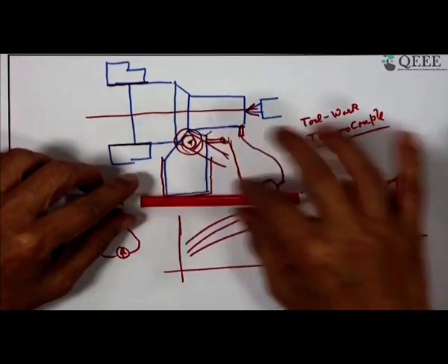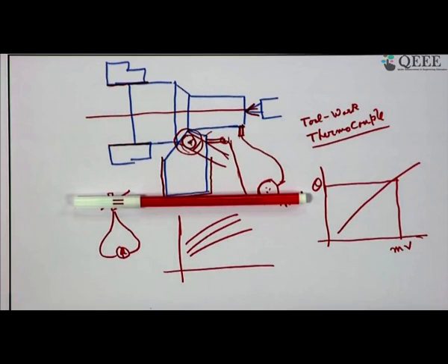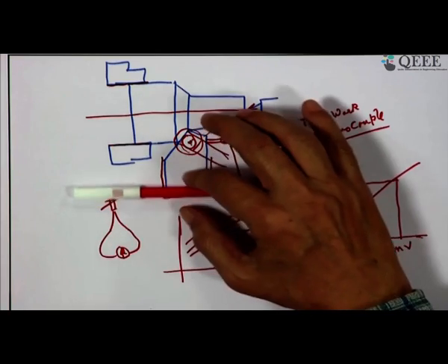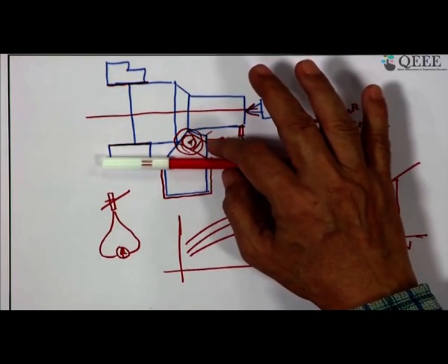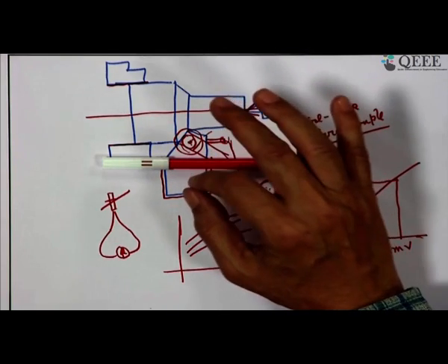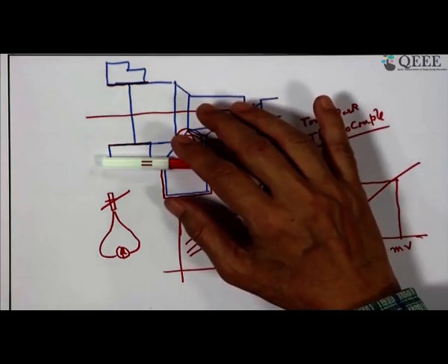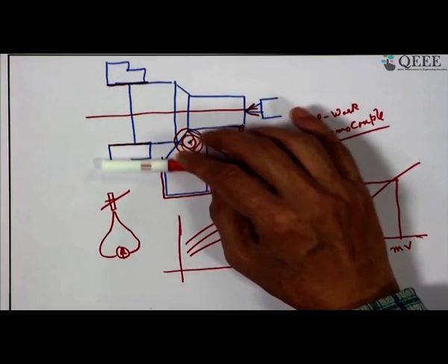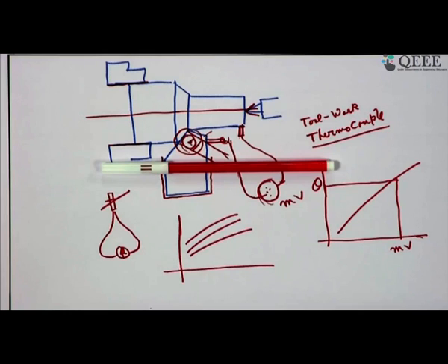Number 2 is that if you do not attain high cutting speed, then also you have to use high speed steel. What would be such a case? You have, say for example, a slender job, 10 millimeter diameter, it is not 100 millimeter diameter. You cannot attain the cutting speed because you cannot have excessive RPM. No, it is not a grinding machine. So, in that case, although the machine is perfect, you cannot attain the cutting speed. So, you cannot always use other tools which are meant for high speed operation with negative rake. So, there also you have to use HSS.